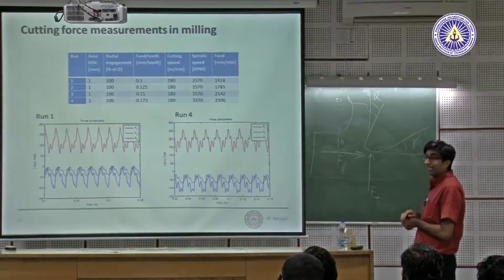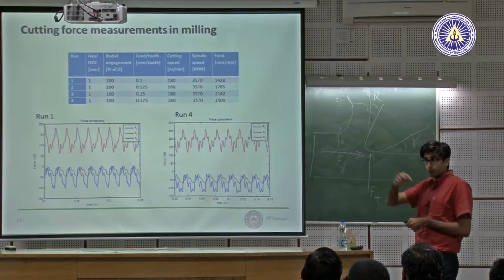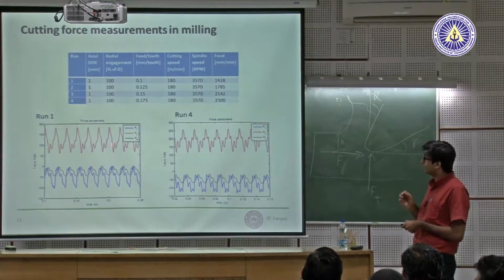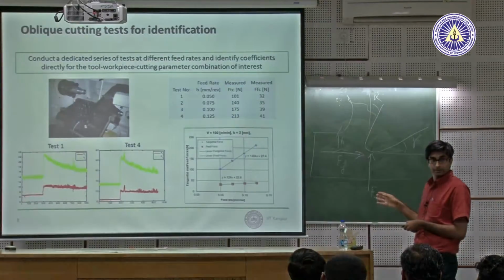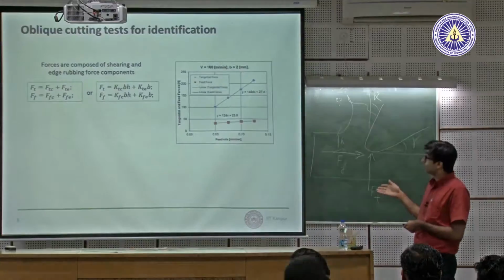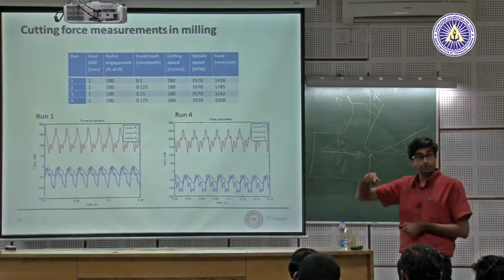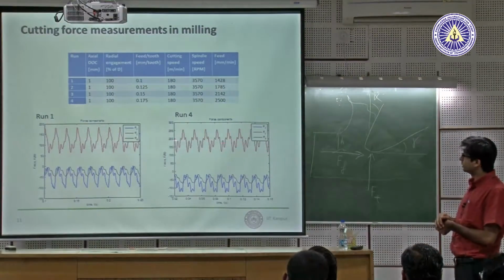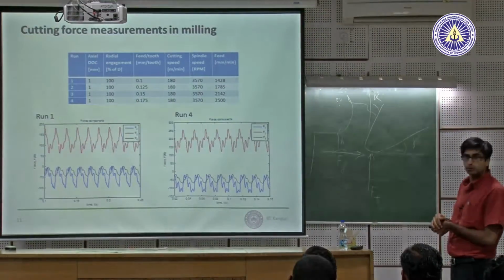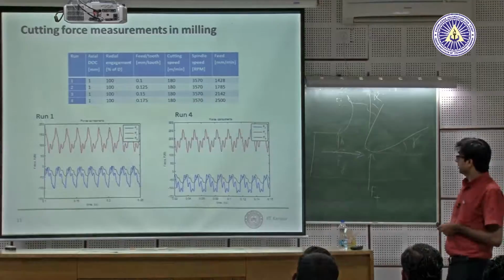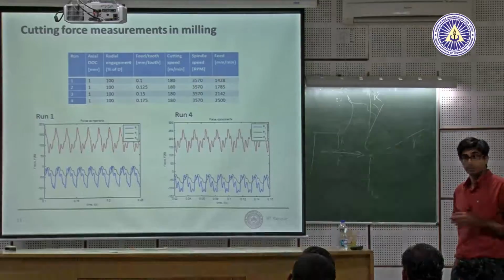And what we will do is called the average approach. So you average the cutting forces over a number of revolutions. In turning, if you remember, your cutting forces are constant, right? Milling, it is not so. So to try and make them constant, we average them over a few revolutions. The average in this case will be about 200 Newton in the Fy. Average in this case will be about 150 Newton, somewhere there. So average them, remember that. And for averaging, you need data over several revolutions.